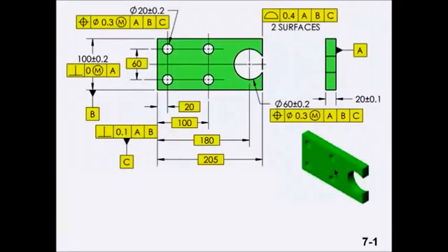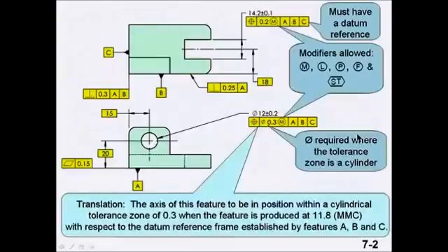Explain that the 60 millimeter diameter feature would be able to trap a gauge pin or equivalent and to establish a reproducible center. Therefore, position may be used to locate this feature. Discuss the two position tolerances. Point out that when maximum material condition or least material condition is applied, there are two ways to look at the tolerance.